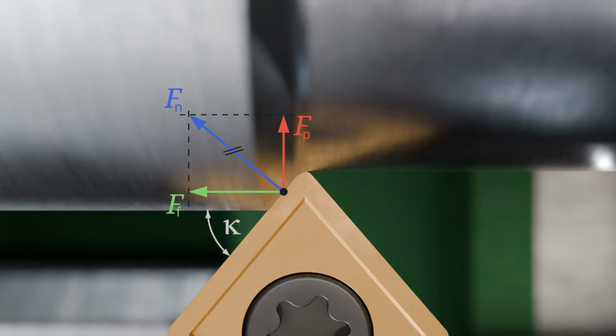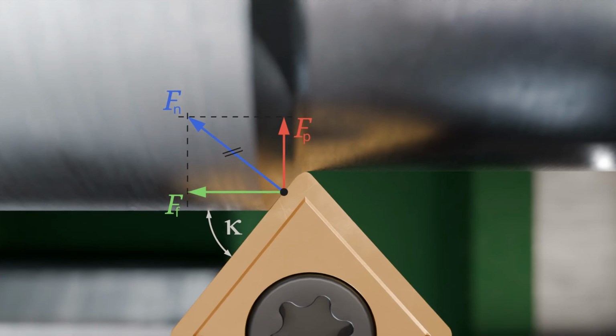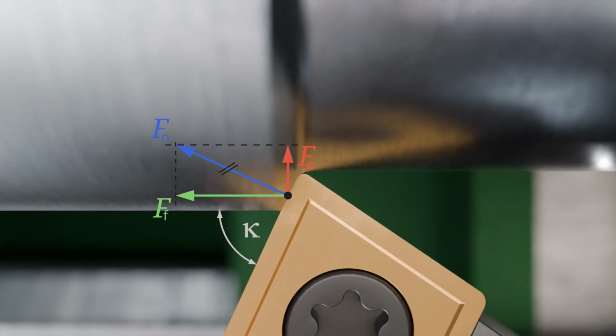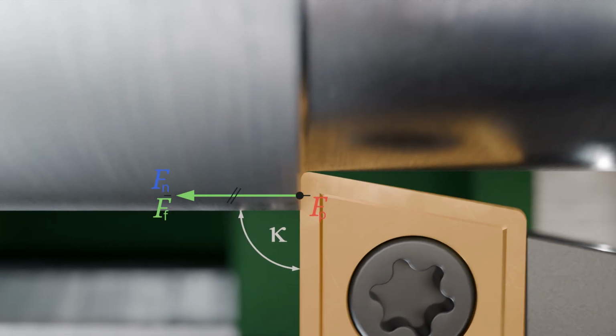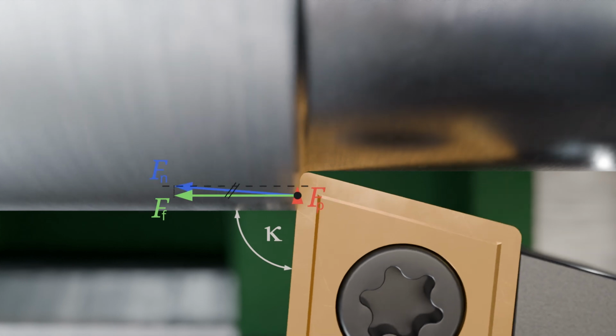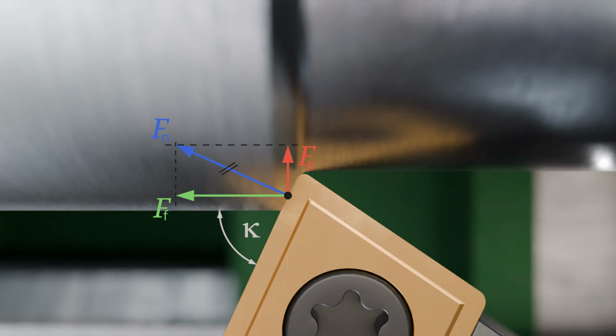The passive force can be significantly reduced by choosing larger approach angles. The force decomposition clearly shows that the passive force decreases as the approach angle increases and even becomes zero at an approach angle of 90 degrees, effectively disappearing. Therefore, during finishing, an approach angle as close as possible to 90 degrees should be used, as this generates minimal passive force. To summarize the most important points, small approach angles reduce the load on the cutting edge due to